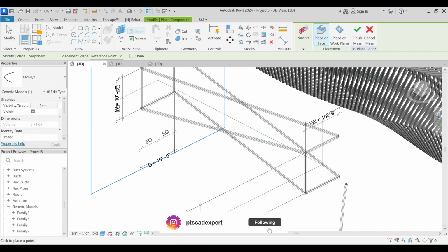And I'll just go to level 1. Okay, and herein I'll just say that reference, and we are going to take into consideration a lot of construction lines for this, a lot of reference lines, and this should be 60. Okay, fine. And I'm just going to copy it multiple times, 5 feet and 5 feet again.